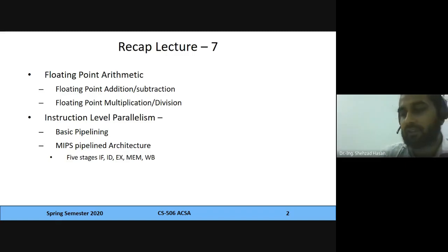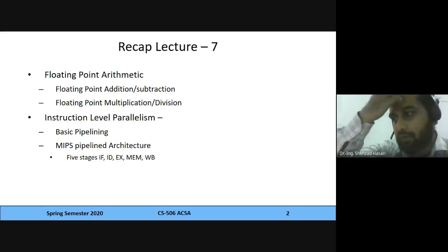So your existing resources are divided in such a way that you break them into stages, and you also prevent the stages from communicating with each other directly by using registers. This allows you to have one instruction per stage, and when the task is complete for that particular stage, it's moved on to the next stage, and so a new instruction can come along. So in the next cycle there are 2 instructions, in the next cycle there are going to be 3 instructions, and so on, right?